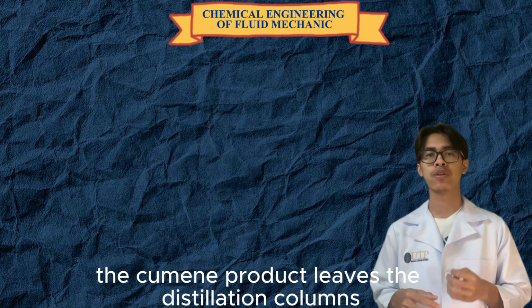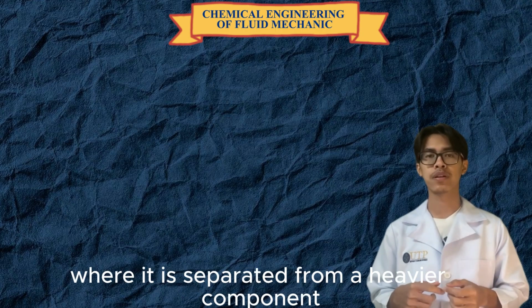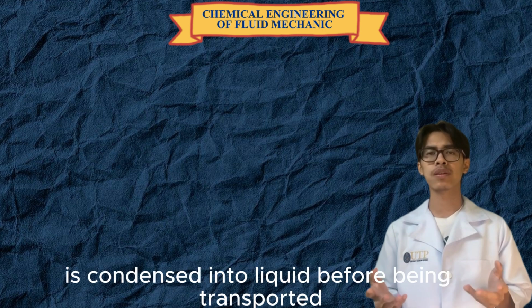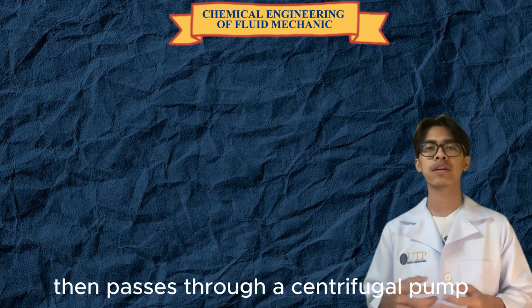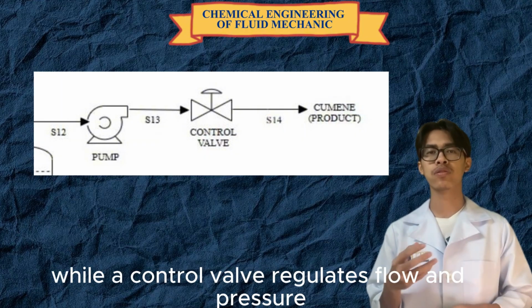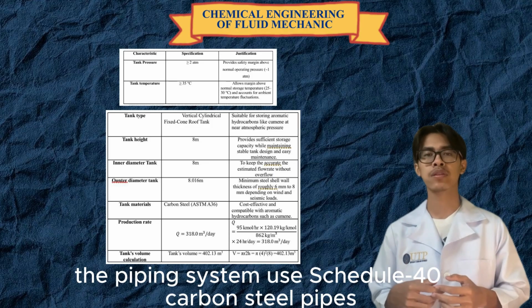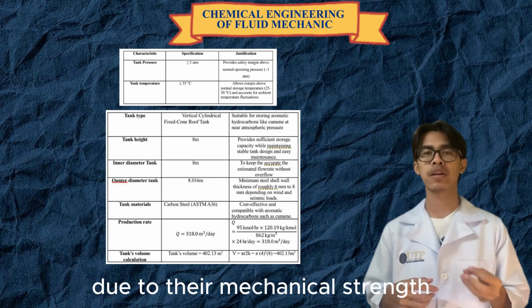Next, the cumene product leaves the distillation columns as the overhead stream, where it is separated from a heavier component such as diisopropyl benzene. The vapor cumene is condensed into liquid before being transported. The liquid cumene then passes through a centrifugal pump to provide sufficient pressure to transfer to the storage facility. A check valve prevents backflow, while a control valve regulates flow and pressure. The piping system uses schedule 40 carbon steel pipes, which are commonly used in petrochemical plants due to their mechanical strength.